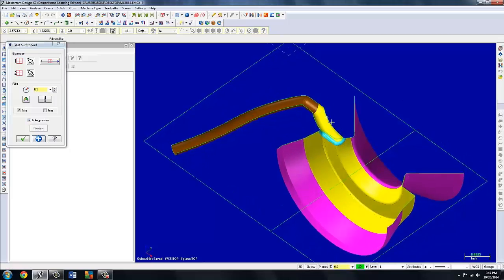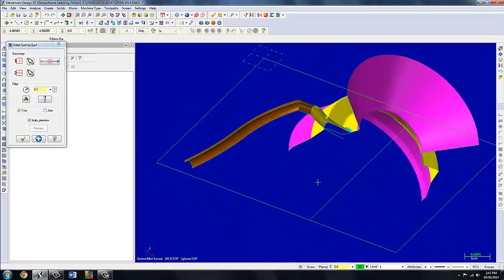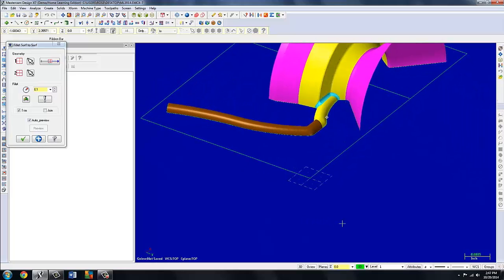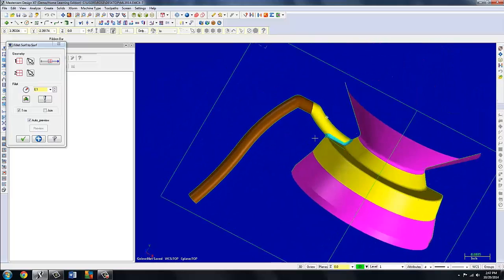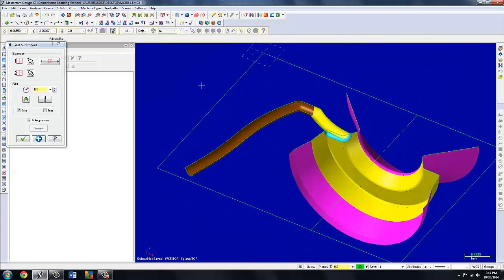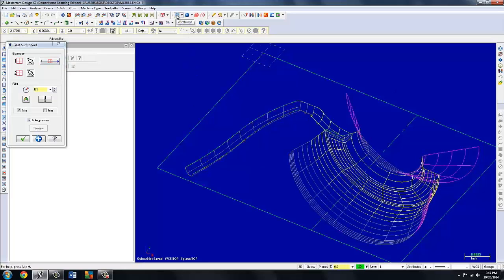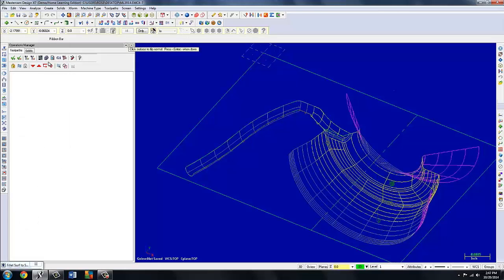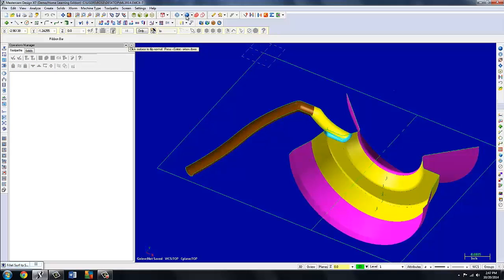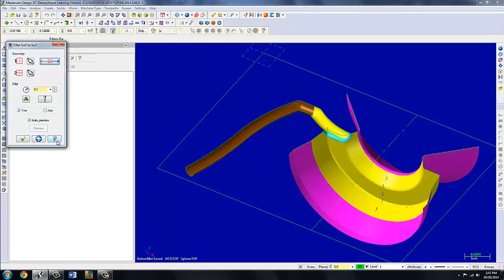It looks good already. It's been trimmed on the inside, and it's all the way around, encompassing those 5 revolved surfaces. So I got lucky, and maybe that's because I practiced, because a lot of times this doesn't work and you have to go back and look at your arrows and flip normals. Sometimes you have to go back to wireframe and look at your arrows, make sure they're all pointing the right way in terms of the logic of the fillet. But we did okay there. I'll just hit enter and check out of that.